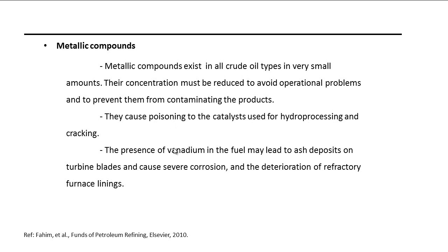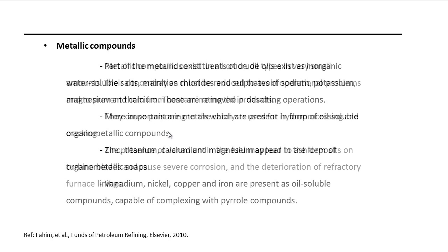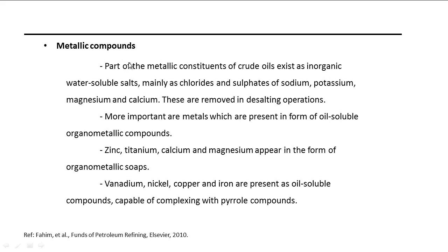The metallic compounds can be present in crude oils in both forms, inorganic water soluble salts and also oil soluble organometallic compounds. And of course, in the inorganic water soluble salts, sulfates and chlorides of sodium, potassium, magnesium, and calcium, these are required to be removed in the desalting unit. We will talk about this in chapter 4.